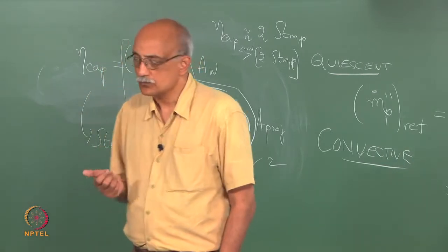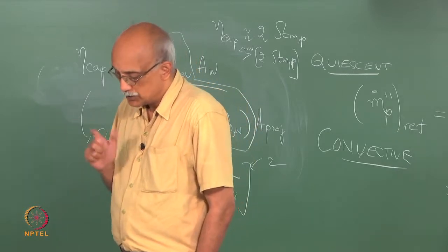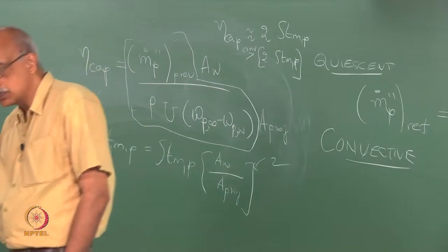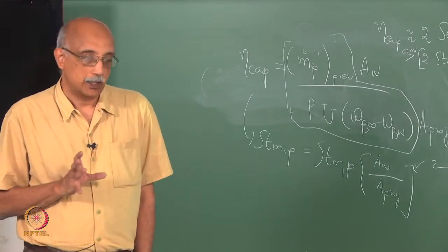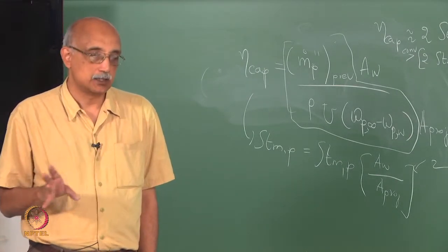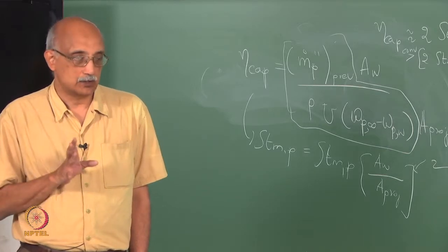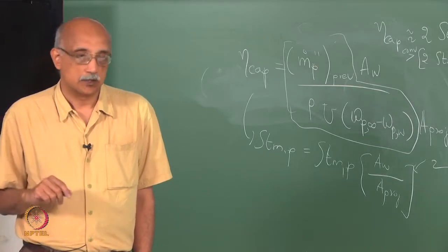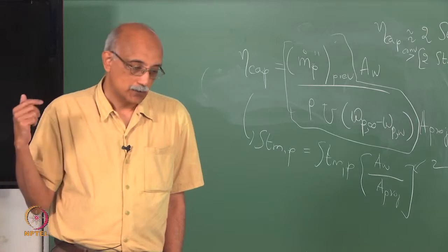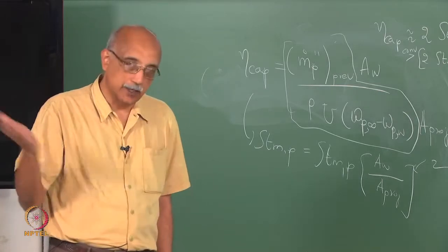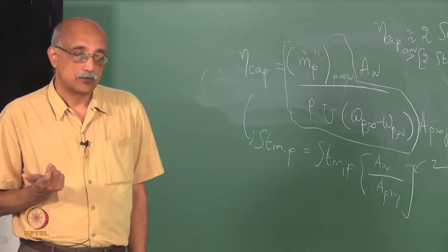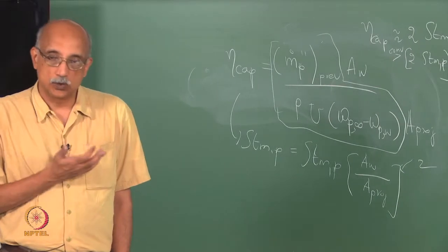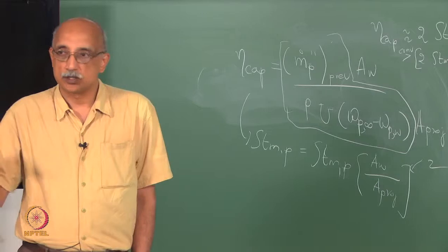And then in terms of particularly the inertial aspect, we said Stokes number is a controlling parameter, and Stokes number also has a first order effect on capture efficiency of particles on a surface. The higher the Stokes number, the greater the probability of inertial capture. However, if you look at particle capture as a whole, there is actually a non-monotonic behavior.